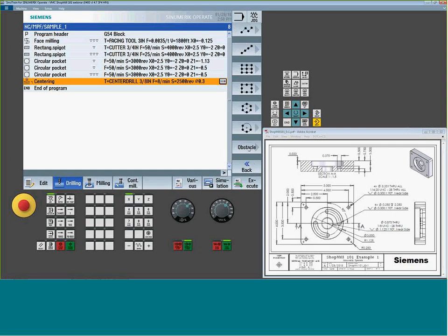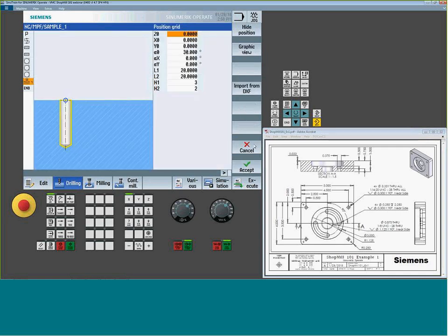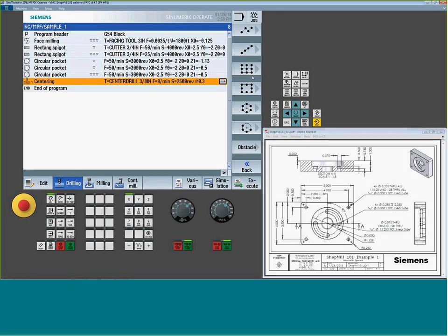So when you go into positions, we got a bunch of different scenarios here. We have random holes, which we're going to use for our 4 outside holes. But I can do arrays, that would be just a linear row of holes. I can do grids. I can do a grid of holes or a frame of holes, and the frame would actually work fine for this scenario as well. And then we can go into bolt hole patterns, complete bolt hole or partial. We're going to use the bolt hole pattern next.